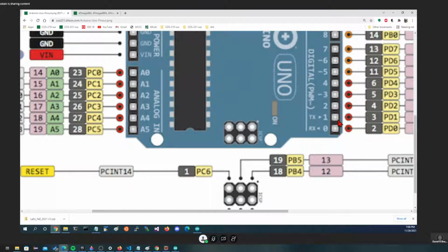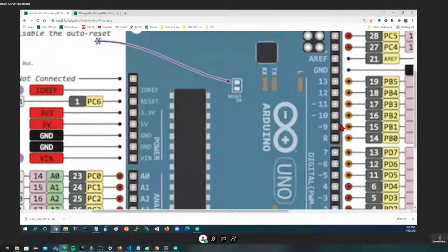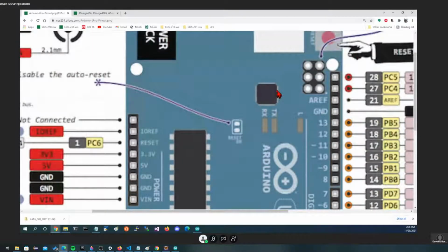We talked about how it's going to add a start bit and a stop bit, possibly a parity bit, and it's going to send it from low bit to high bit, then the parity bit. So it'll be start bit, low bit through high bit, potential parity bit, and then a stop bit. That'll be sent on the board up to this chip right here.